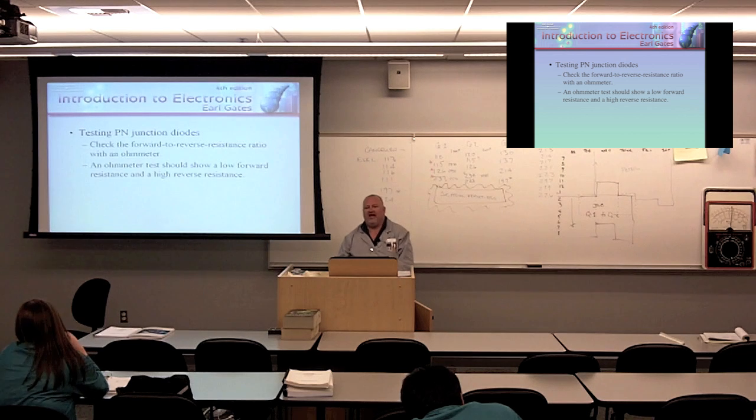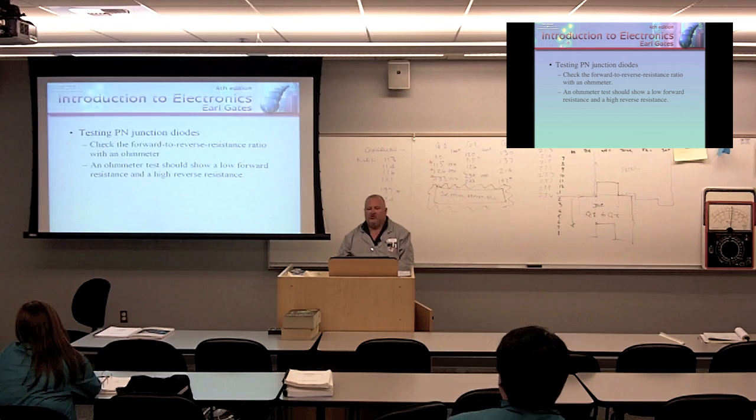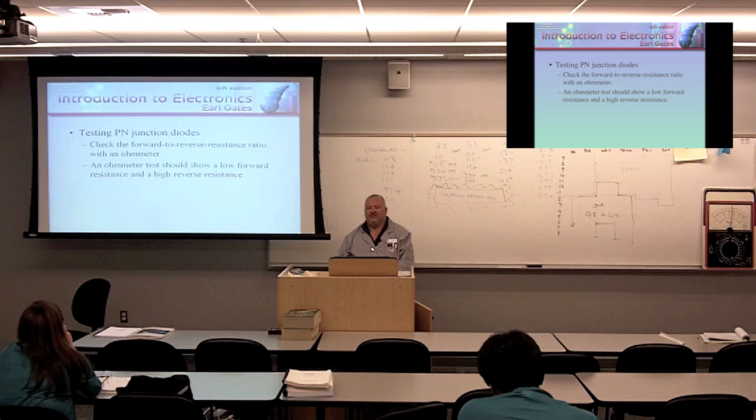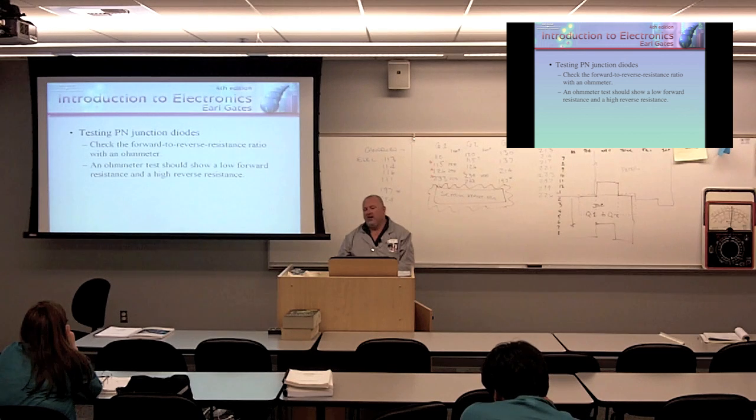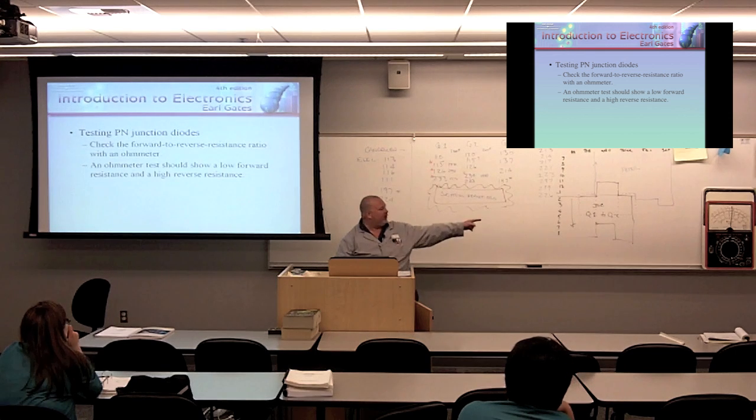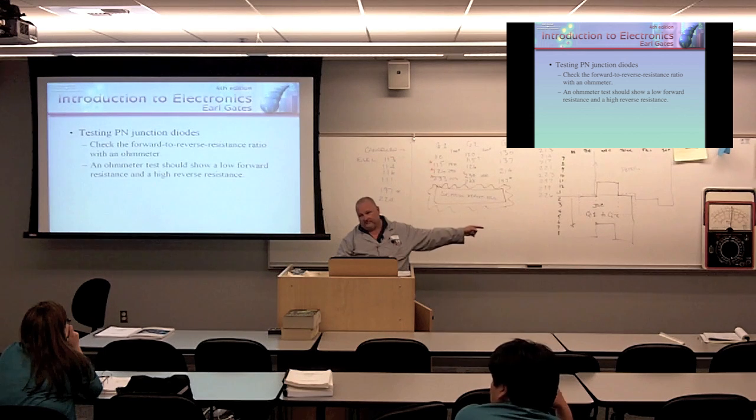Testing PN junction diodes, real easy. Check the forward to reverse resistance ratio with an ohm meter. One of the things I want to point out to you is when I say ohm meter, I am talking about an old school analog ohm meter. That's what I'm talking about.